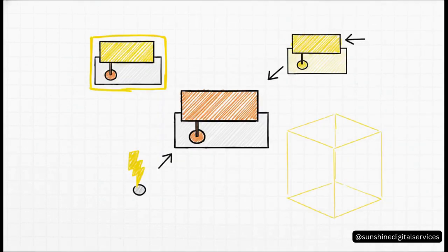Okay, the model is built, but now we have to get it ready to simulate. We use that unite command to make the patch and feed one single object. Then we assign boundaries, telling HFSS that the metallic parts are perfect conductors. Then we add an excitation, which is basically like hooking up a virtual cable to the feed line to inject our test signal. And last, we draw a big box around the whole antenna to tell the software, hey, calculate how the signal radiates out into the space.